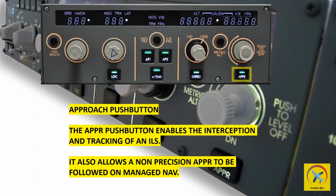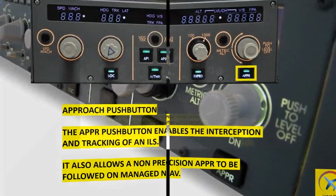If the localizer or approach button is selected on and the ILS button is not selected, and an ILS approach is entered in the flight plan or the radio NAV page, ILS flashes amber on the PFD. If the ILS and approach buttons are selected on when a non-ILS approach is selected in the flight plan, vertical deviation flashes amber on the PFD. If a VOR or NDB approach has been selected in the database, the localizer and approach buttons will not arm for localizer or glide slope capture, even if the ILS frequency is manually tuned. An ILS approach must be selected via the flight plan page.